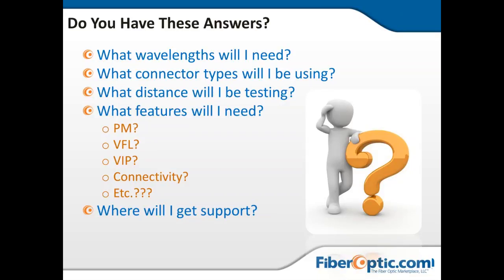What connector types are we using? As I mentioned, we typically will have a connector that is sitting at the end of the fiber under test. So that fiber under test is really going to be the connector or the port at which we're going to make our physical connection. And there's a couple things to consider. One is, are you plugging the OTDR directly into the fiber? Hopefully the answer is no. We really don't want to do that.